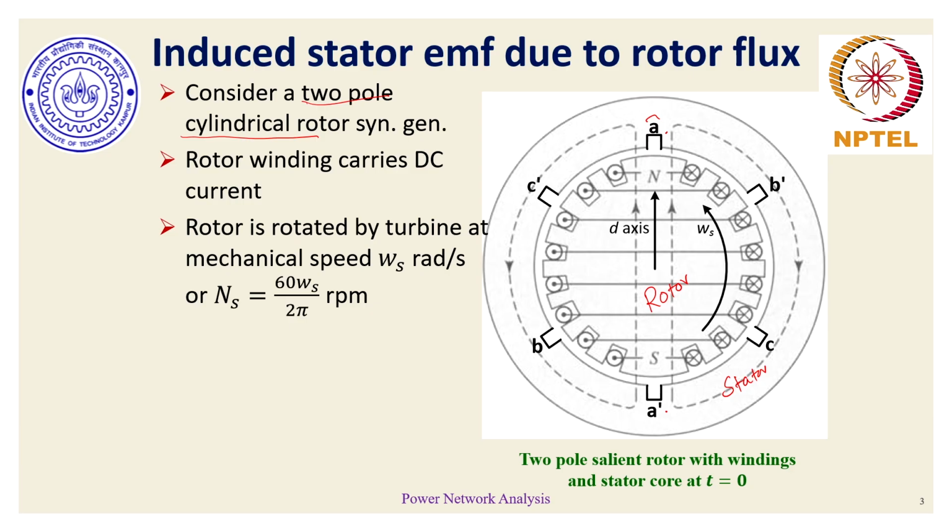If I have to see the orientation of phase A, phase B, phase C incoming conductors, and mark the corresponding arrows somewhere like this, and find the angle between each of these arrows, these angles tend to be equal to 120 degrees apart, which essentially means that the stator windings are again 120 degrees electrically spaced apart in the stator core. So that serves the purpose of the electrical construction of the stator core.